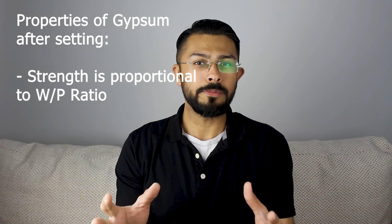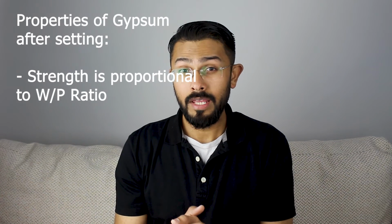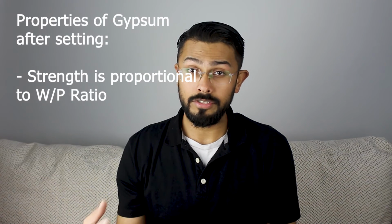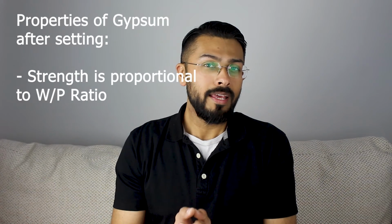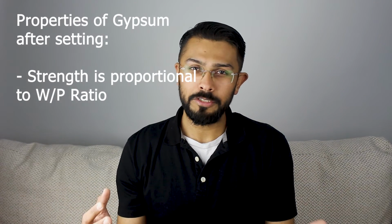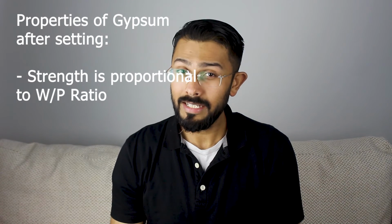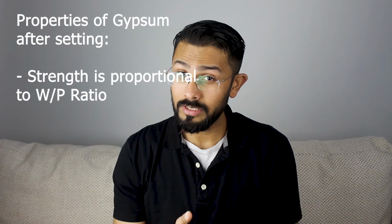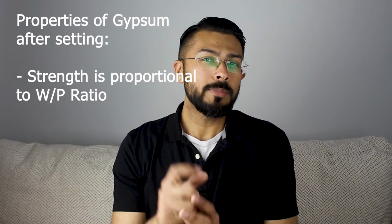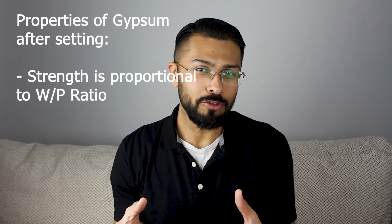The strength of gypsum depends primarily on the porosity of the set material and the time for which the material is allowed to dry out after setting. The porosity and hence the strength is proportional to the water powder ratio. Since stone is always mixed at a lower water powder ratio than plaster, it is always less porous and consequently much stronger and harder.